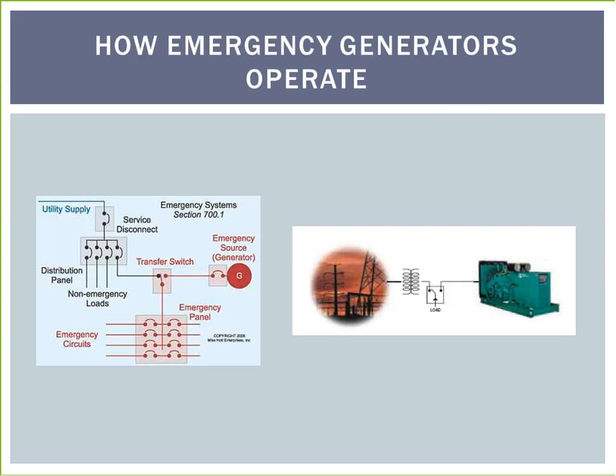If no electricity comes in on the normal side, the transfer switch uses a solenoid to throw a triple pole single throw switch. This switches the feed from normal to emergency power. The loss of normal power also triggers a battery operated starter system to start the generator, similar to using a car battery to start an engine. Once the transfer switch is switched and the generator starts, the building's emergency power comes on, after going off when normal power was lost.